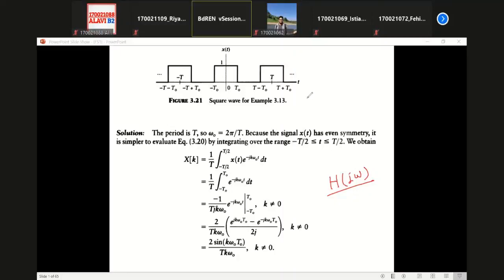will illustrate today. Now you see that this is a square wave, and this is your time origin. With respect to the origin, is this function an even function or an odd function? Even. It is an even function. But when we are using the exponential type Fourier series, we usually do not think about the symmetry condition, because we have to determine only one Fourier constant, xk. Now, if you want to express this square wave as a series of complex exponentials, we have to find the Fourier constant xk.